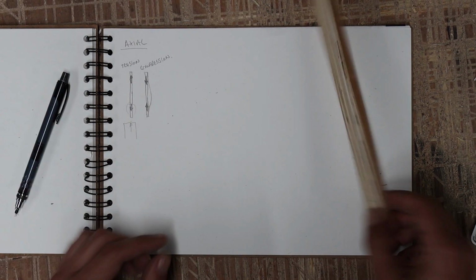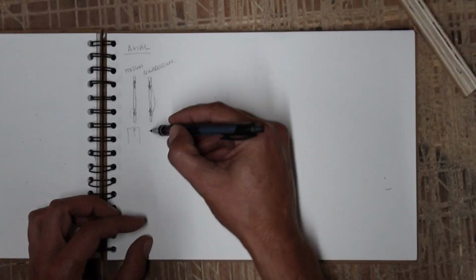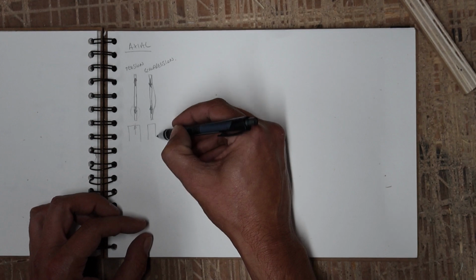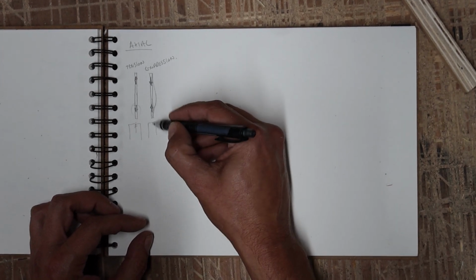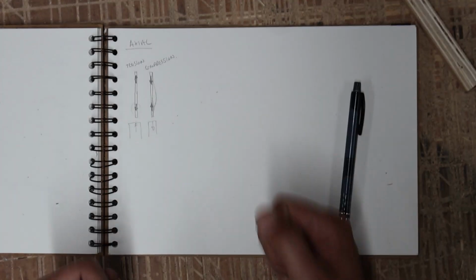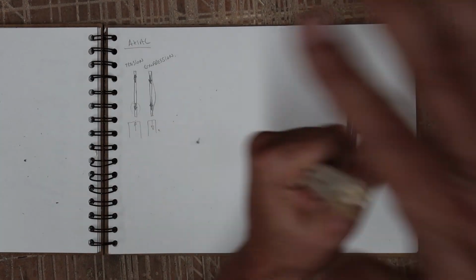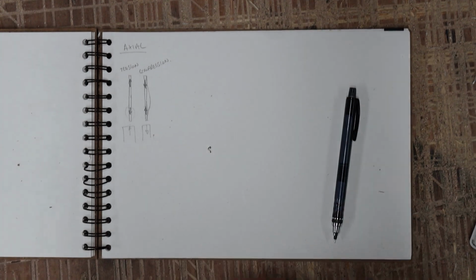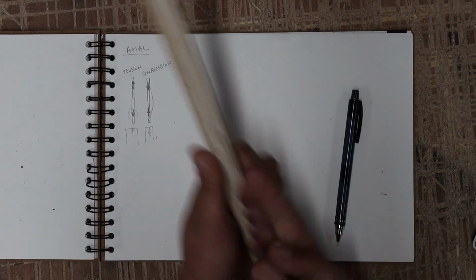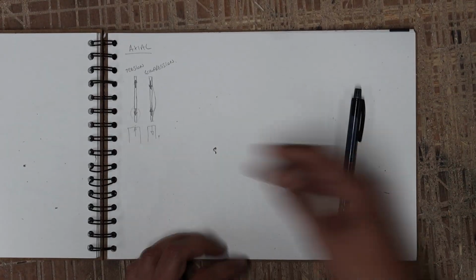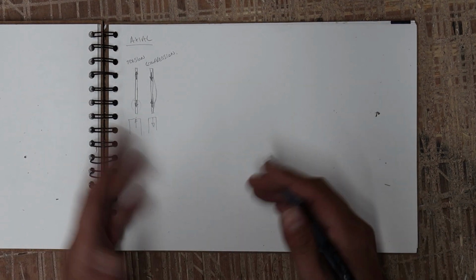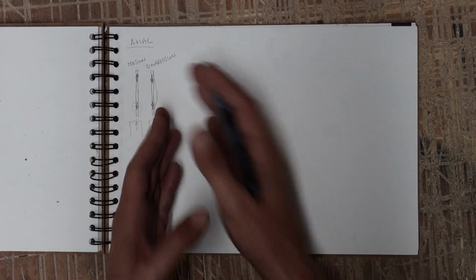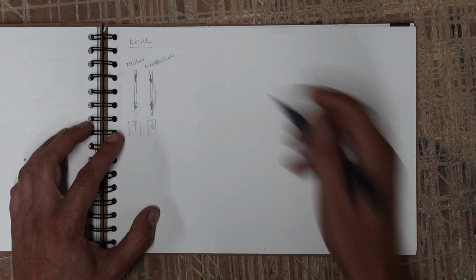That's how that phrase, every force has an equal and opposite reaction, works its way into structures. So in much the same way in compression, if we had a structure down here, then the reaction to this force would be the opposite. It would need to go downwards. If we imagine we're pushing downwards onto this, that's pushing down onto the page, but the force in the member is going up. So those are axial loads, tension and compression. They're the only two we need to worry about.